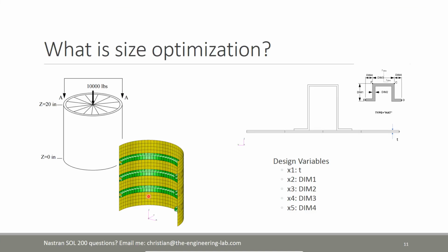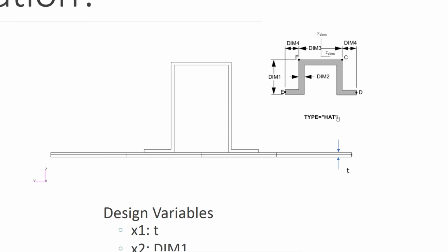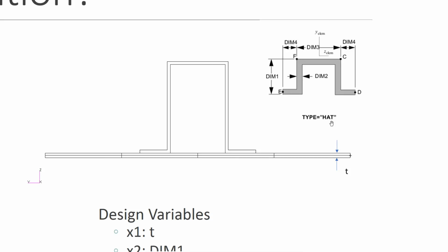Back to the presentation. So here's our structure. We zoom in on it and there's nothing too impressive about it. For example, the two-dimensional yellow elements here, these actually have a thickness associated with them. And it's not until we specify parameters to these elements that they finally have significance. Again, we applied a thickness parameter to the two-dimensional elements. We specified beam cross-section dimensions to the line elements that you saw a moment ago.